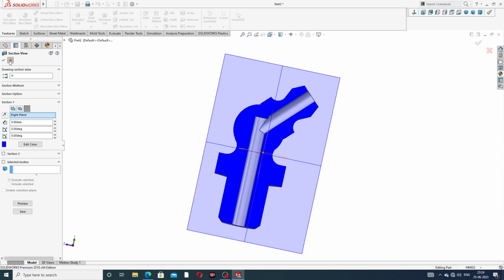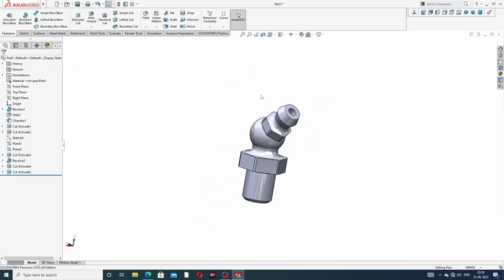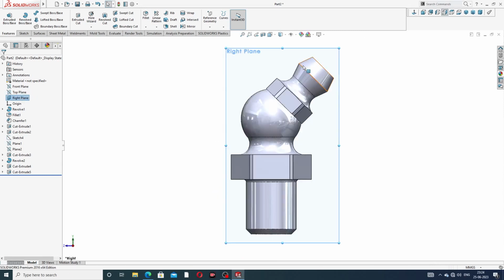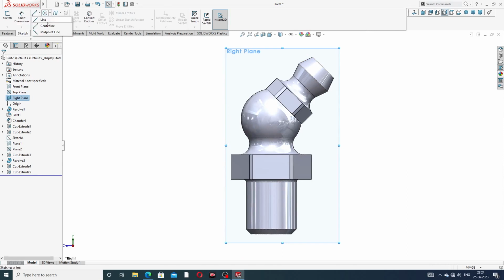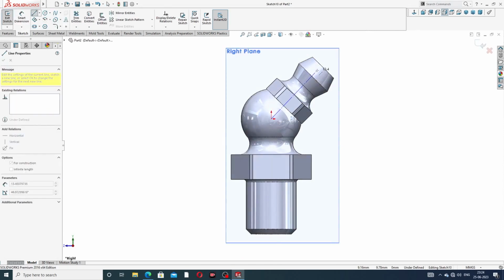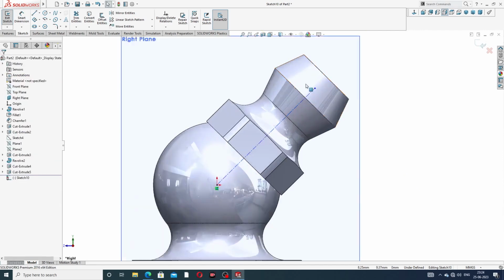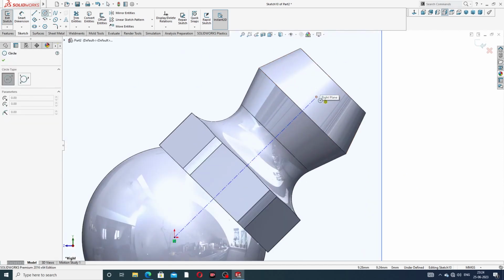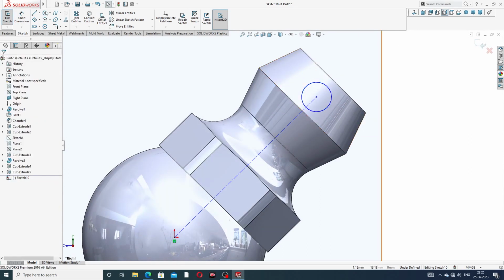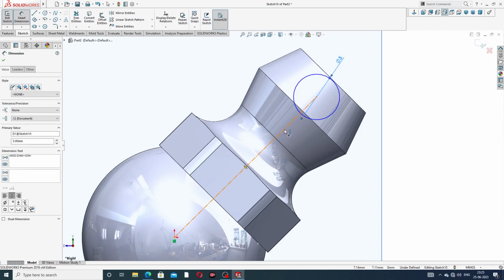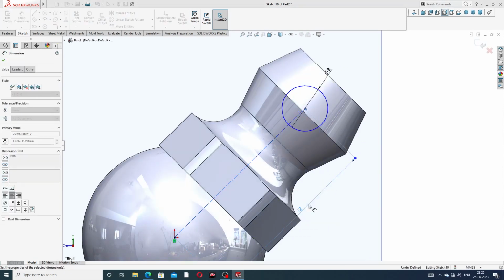and okay, and next use this ball, okay, and use the right plane, sketch normal, and use a center line from this to this. Okay, a circle is drawn here. This diameter is 3 millimeter, and this distance is 12 millimeter. Okay,